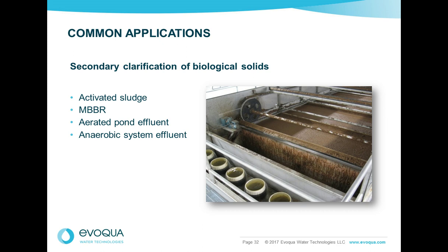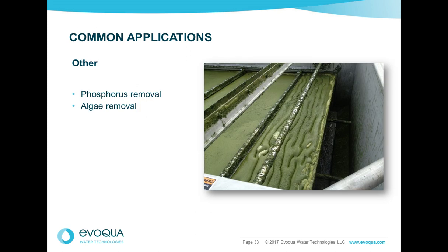Flotation is also becoming more commonly used for clarification of biological solids, like those coming from an activated sludge system or a moving bed biological reactor or just an aerated pond effluent, and even anaerobic systems where clarification of biological solids is necessary for effluent quality downstream. In recent years, we've been seeing a lot more applications for tertiary treatment where phosphorus removal is important.